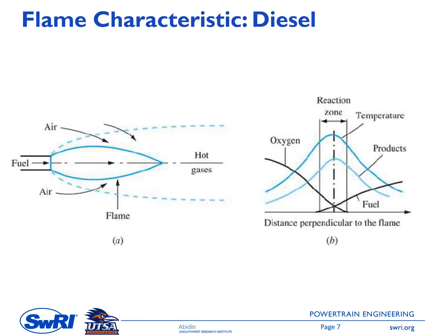Next one is the flame characterization for the diesel combustion. In the diesel engine, we have non-premixed, turbulent, and unsteady flames. This figure is showing the schematic of the non-premixed flame inside a diesel engine. This is the structure of what is sometimes also called a diffusion flame.